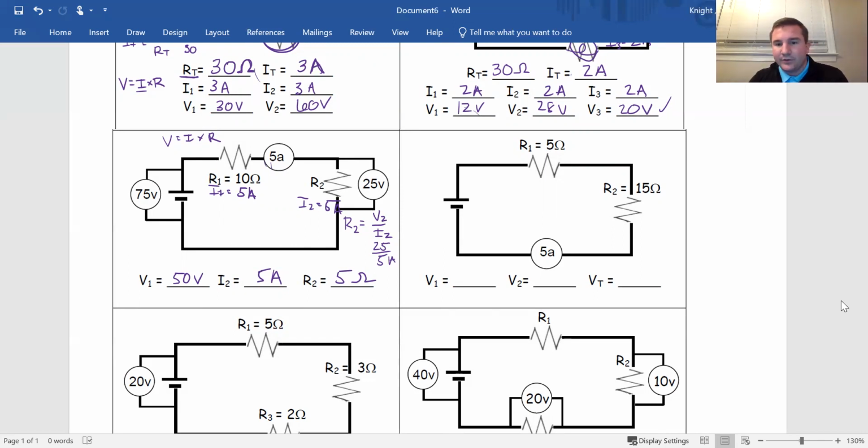Here, we want to know the voltages of each part of the circuit. And we know that the current is 5 amps. So current up here, I1, 5 amps. Current over here, I2, 5 amps. Current through every part of the circuit, even the current through the battery, 5 amps. It's 5 amps everywhere. And now that we know the current, we know voltage is current times resistance.